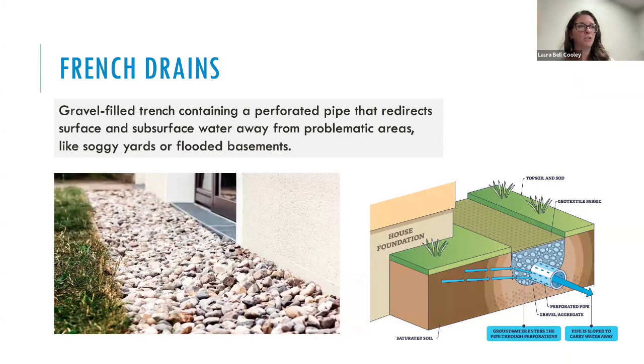I just want to quickly mention French drains. For the Rain Ready program, French drains are not necessarily included by themselves unless they're part of a system that helps manage stormwater from one location into a treatment area like a rain garden or a bioswale or something like that.